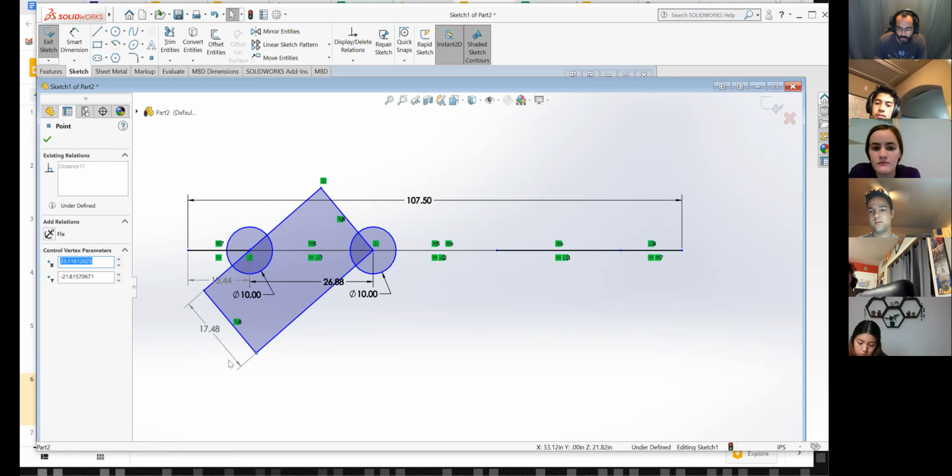Yeah, so it's just anytime you have rotation that's happening in a different direction than a roller, it's either another motor or some sort of mechanical linkage to get that kind of perpendicular rotation. Yeah, so that way it gets a little bit trickier to do, where there's multiple other examples of feeding balls back to the center and centering with intakes. One of the ones was mechanism wheels, or what are often now known as vectored intake wheels, can help with that because you can bring them in on the single roller, but they kind of get driven into the center already. So even if you have a wider intake, you can still bring the ball in to the center where you want it to be.